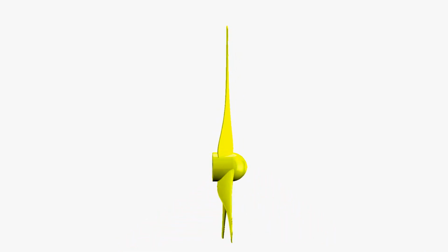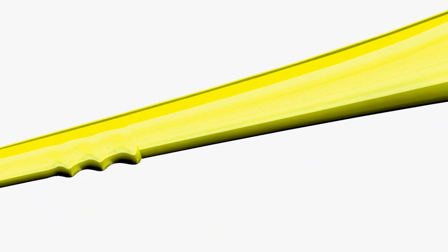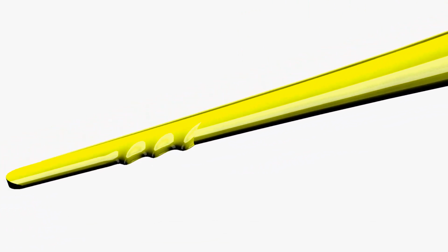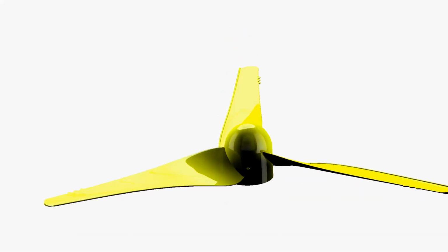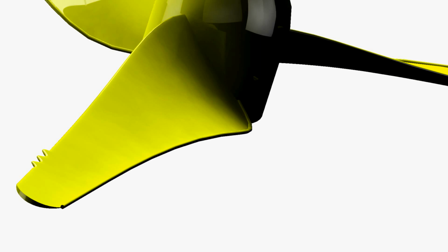Adding the tubercles requires us to calculate the optimal wavelength and amplitude of the tubercle spacing. Based on studies, generally the shorter the wavelength, the better the aerofoil performs in terms of maximum lift, stall characteristics, and drag. However, this improved performance is bounded by the amplitude of the tubercle. We therefore need to find a compromise between these two factors. Finally, when modeling the wing, we also decided to have a rounded trailing edge due to the limitations of the 3D printer. By having a rounded trailing edge, we are then able to sand it down.